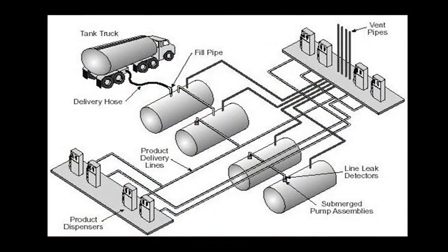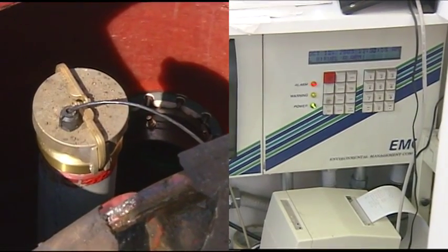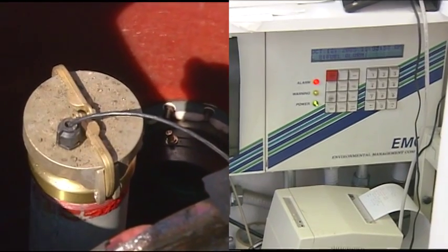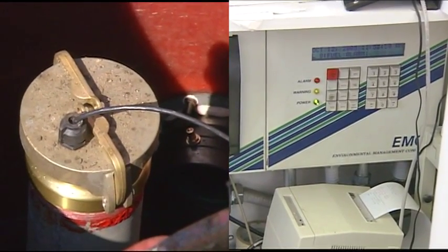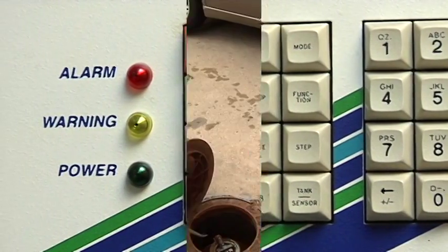The dispenser is connected to the underground tanks by a piping system. A line leak detector is installed in the piping system to detect a catastrophic release. This detector, if activated, will either shut off the flow or set off an alarm, depending on your location. Be sure you know which type of system is used at your location.